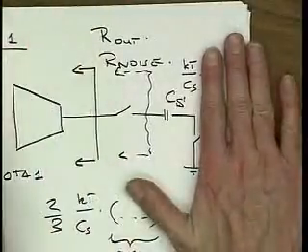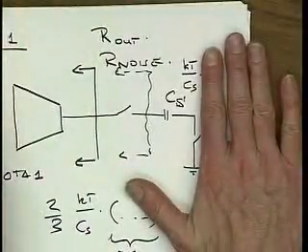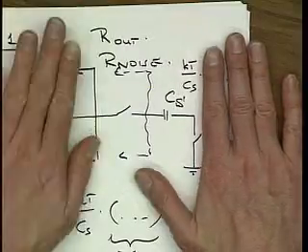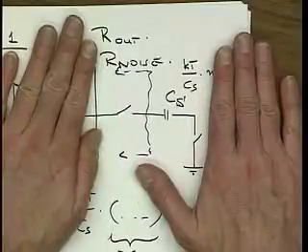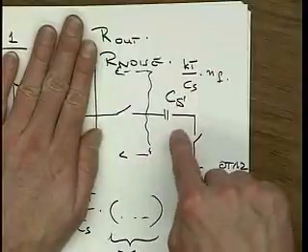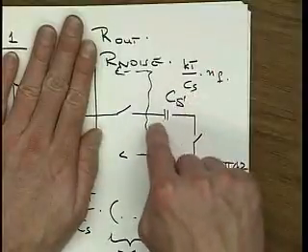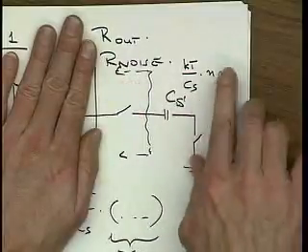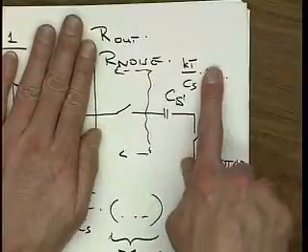Whoever buys the A to D converter has to stick a signal into it. When we design A to D converters, we always spec them for the case where R out equals R noise, and so this factor NF is equal to 1.